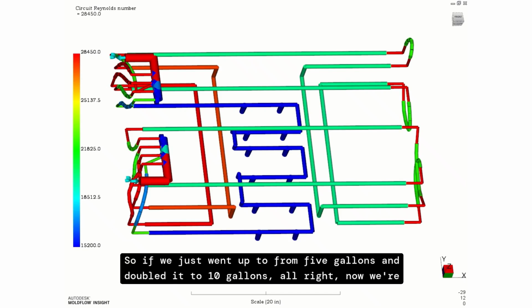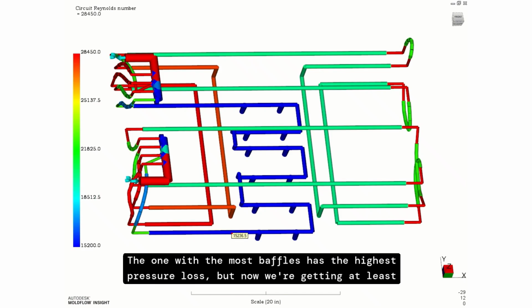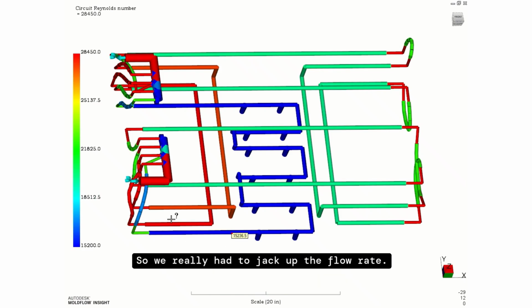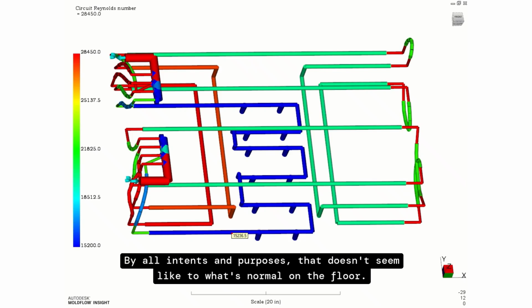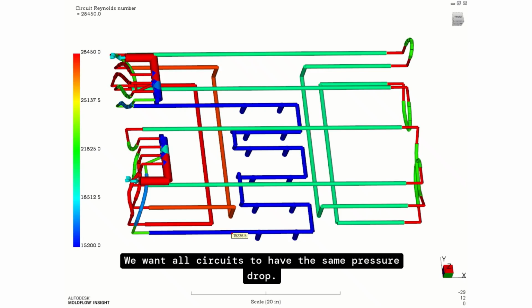So if we just went up from 5 gallons and doubled it to 10 gallons, now we're getting our turbulent flow in the most critical circuit, if you will. The one with the most baffles has the highest pressure loss, but now we're getting at least 15,000 in there. So we really had to jack up the flow rate. By all intents and purposes, that doesn't seem unlike what's normal on the floor. But if we look at this from an efficiency perspective, this is very inefficient. We want all circuits to have the same pressure drop. So what do we want to do to the circuits?